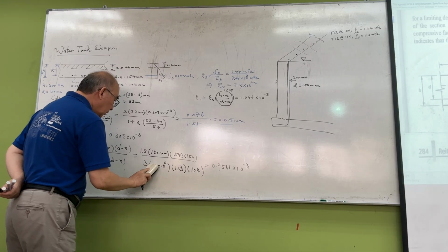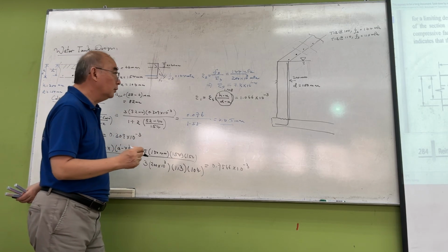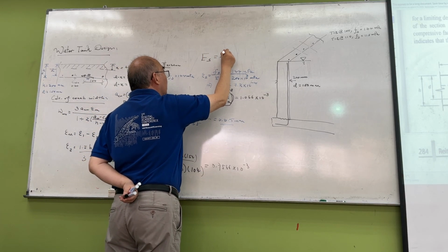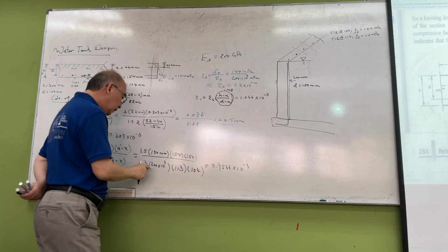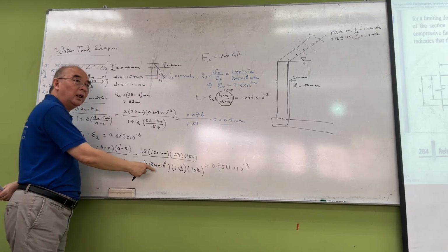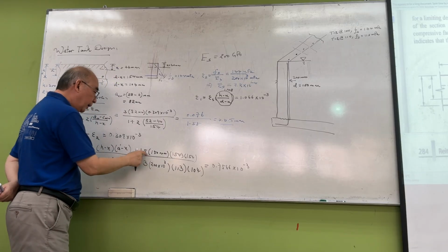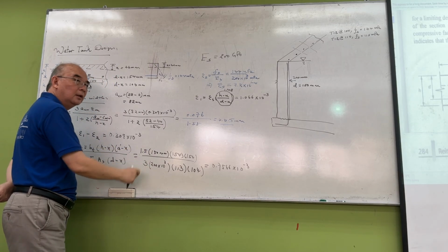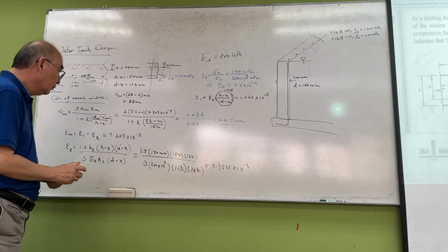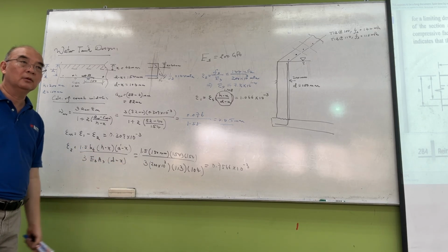Remember, this Es is normally quoted as 200 gigapascal. But this Es here, we need to put as MPa rather than GPa, because this will match the units here, 1.5 MPa, the apparent concrete tensile strength. Did I do my calculation correct? Especially this one.